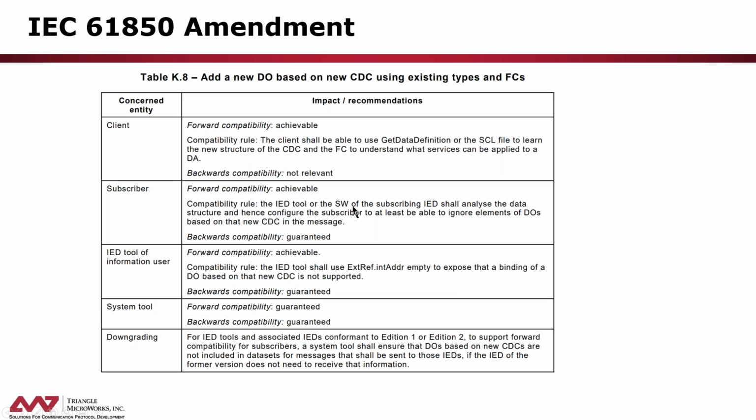I have a mechanism, I can analyze the data structure. I can see the data set members. I can see the list either by interrogating the device or by reading the SCL file. I can get access to the data type templates. I can understand the structure of the CDC. I know the data types of each member of the CDC.